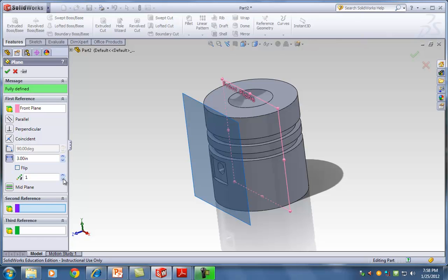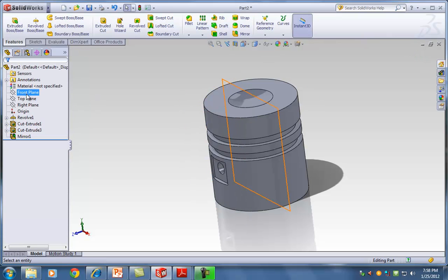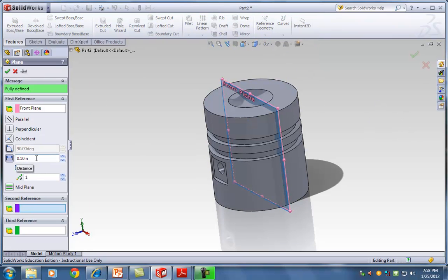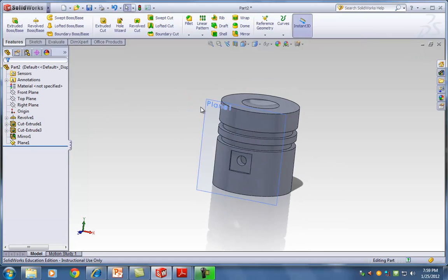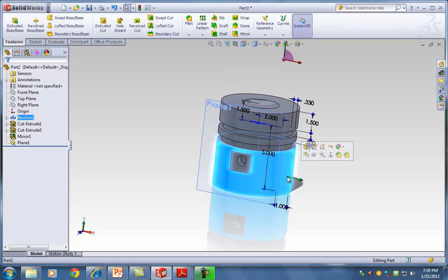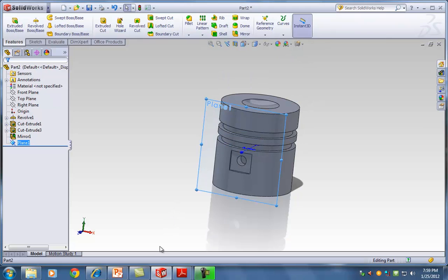Any questions on that? Can you go over the part again where you put the reference geometry and then change it? Okay, we're going to click on the front plane, reference geometry, and plane. Then over here on distance, we're going to put 5. Sorry, 3. Now, notice if you want to move this blue plane to the back, all you have to do is click on the check mark that says flip. Okay? Now I'm going to hit check mark. So now I can select this plane as its own plane. Anything that I said before about not being able to draw directly on this face, well, now I can on plane 1.